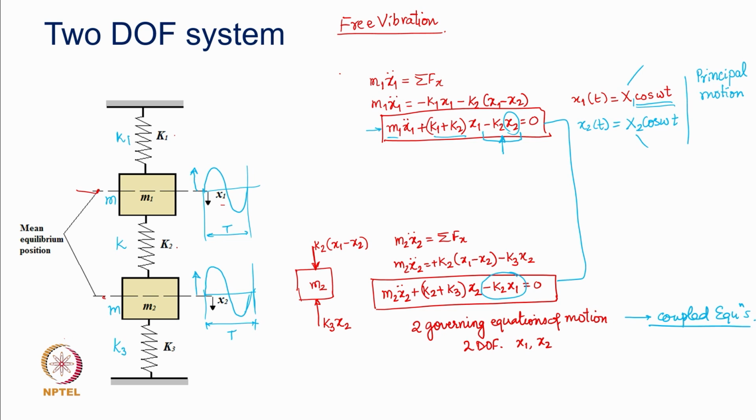Where all the elements of the vibratory system, elements I mean M1, M2, would move harmonically with the same frequency and they would complete their one cycle of motion at the same time. So, they would start at the same time, end at the same time, and when that happens, you can imagine that they are perfectly harmonic, they are perfectly moving with the same period, and then the whole motion looks like a harmonic motion.